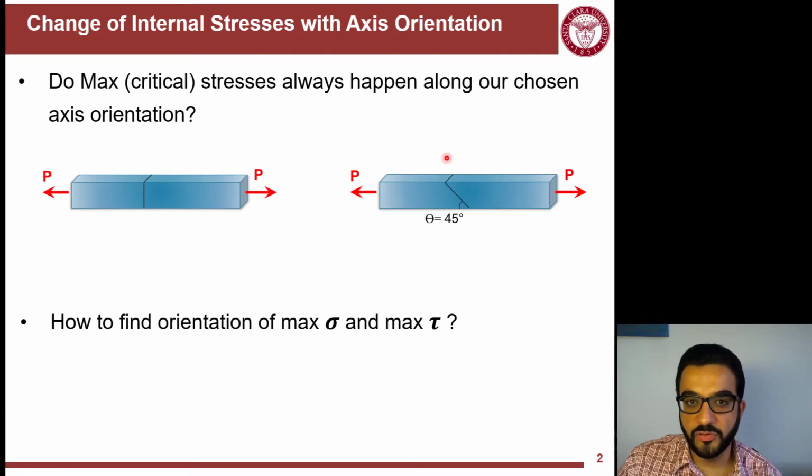And that was a case to show you that even if we have this cut perpendicular to this axially loaded member, here we have only axial loads or normal stresses. But when you cut at 45 degrees, you start seeing shear stresses. So that was an example early in this course that generally your cut affects the generated stresses on such a cut.